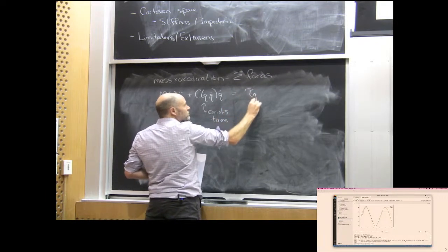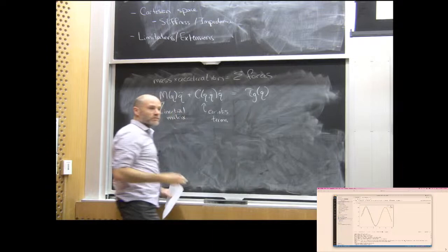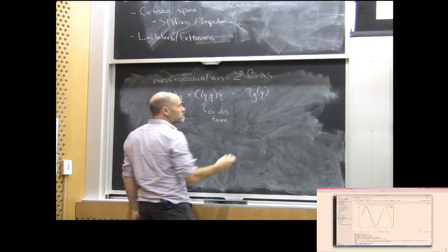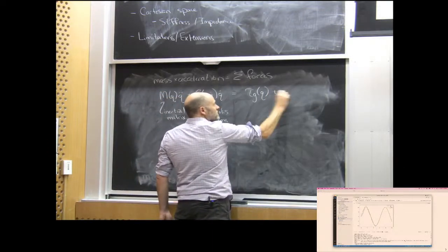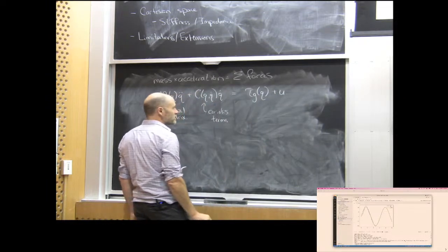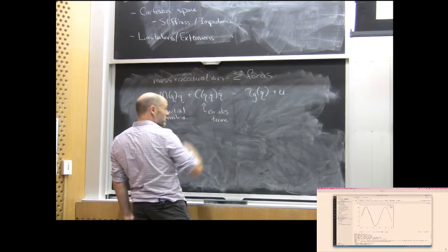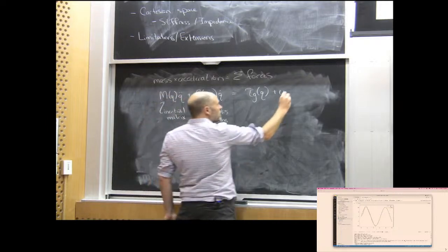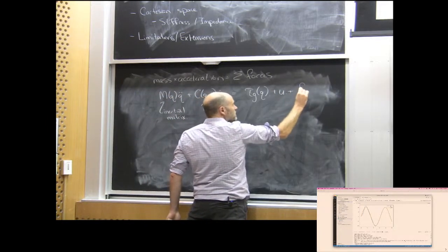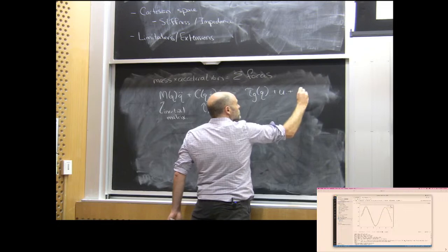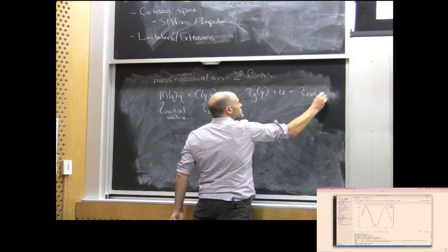So you get the gravity forces, which in general are some function of the configuration. I'll assume that I've got U's everywhere, so I'll just say I can command every coordinate. And then I can have, I'll write it as a torque now, a tau external.